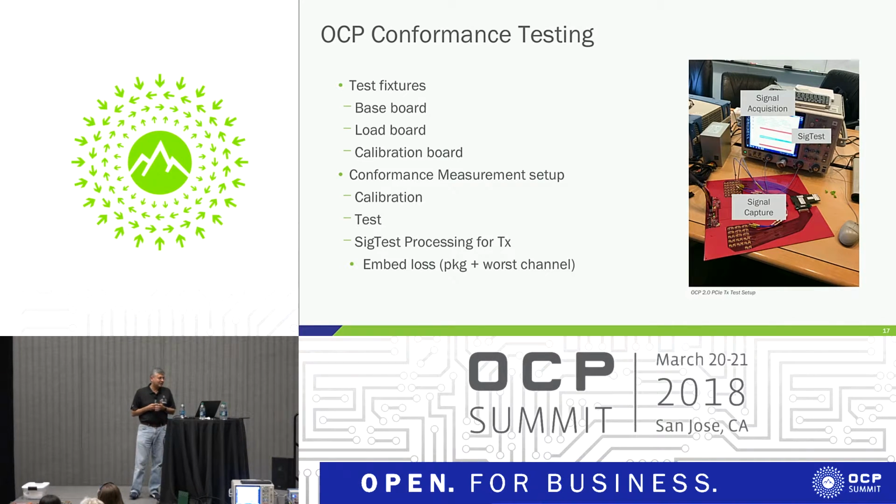So now, like I was indicating, the concept of doing this conformance testing, we wanted to keep it the same. There are two basic tests which we are trying to focus on right now: the transmit signal quality, and also the receiver sensitivity and the jitter tolerance. That's how we are starting slow, small, and then we will eventually bring out more. There's PLL bandwidth testing, which is also part of the PCI electrical testing, which right now is not in the scope of work at this point. But the concept is very similar.